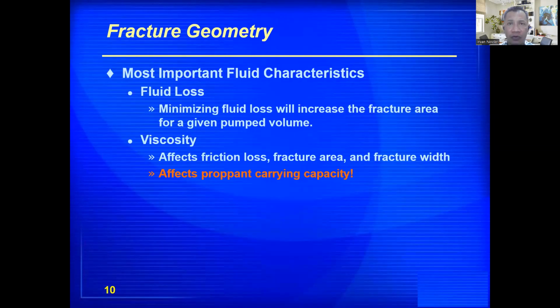The most important fluid characteristic, number one, is fluid loss. If you minimize that fluid loss, you are going to increase your fracture volume for a given total pump volume. Okay, the other one, viscosity, affects friction loss, fracture area, and fracture width. The most pressing factor here is that it affects your proppant carrying capacity.